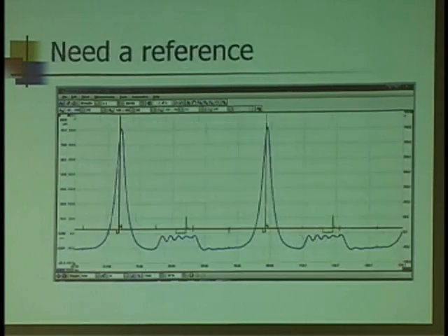Let's give a reference. This is showing the in-cylinder pressure, so the peak of the blue trace is top dead center of compression. There's my ignition event occurring just before that point. The injector event's actually occurring closer to TDC of what? The exhaust stroke, right?